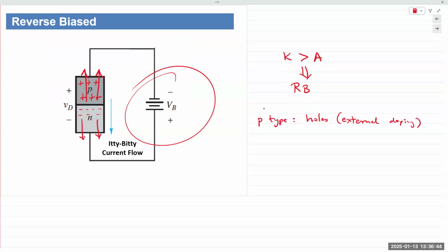Plus intrinsic, the thermal effects, you also have holes. And because these are larger in number, these are known as the majority carriers. Both holes and electrons carry the charges, hence they are known as charge carriers. In a p-type material, holes are referred to as majority carriers, and electrons are labeled as minority carriers.